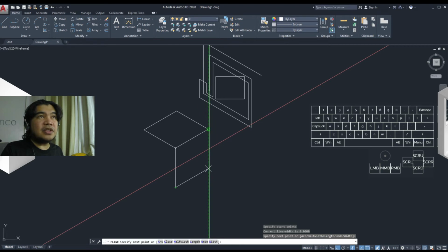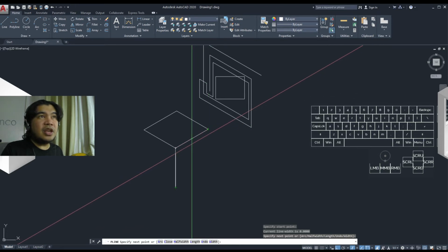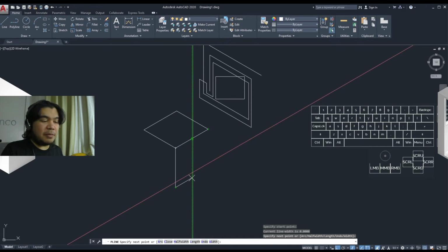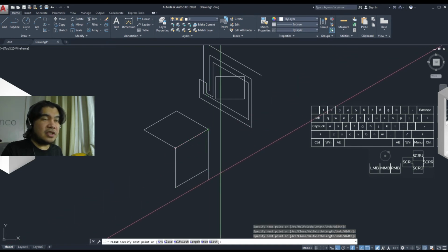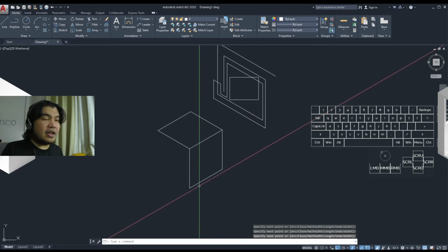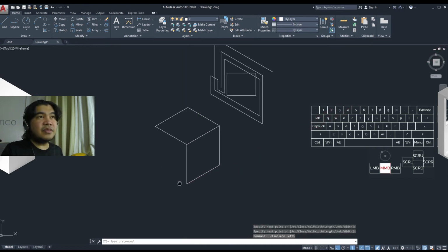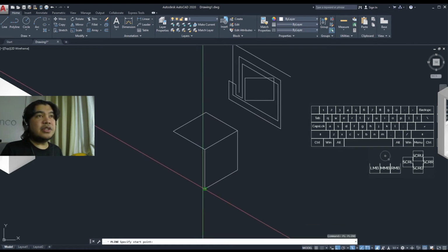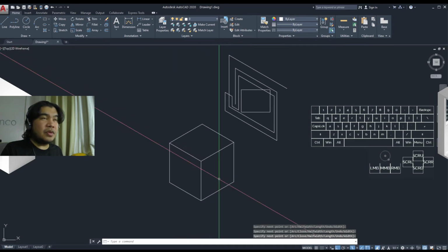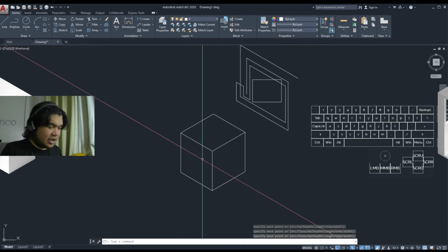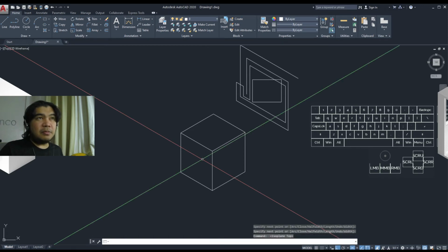How that happens is you find a snapping point and then when you move your cursor around, it uses that snapping point as a reference. So again, we'll do this to complete that phase. And then once again, F5, and we're back to the first orientation. So this is the better way to understand it, when you cycle through top and bottom, right side and forward, left side and forward.